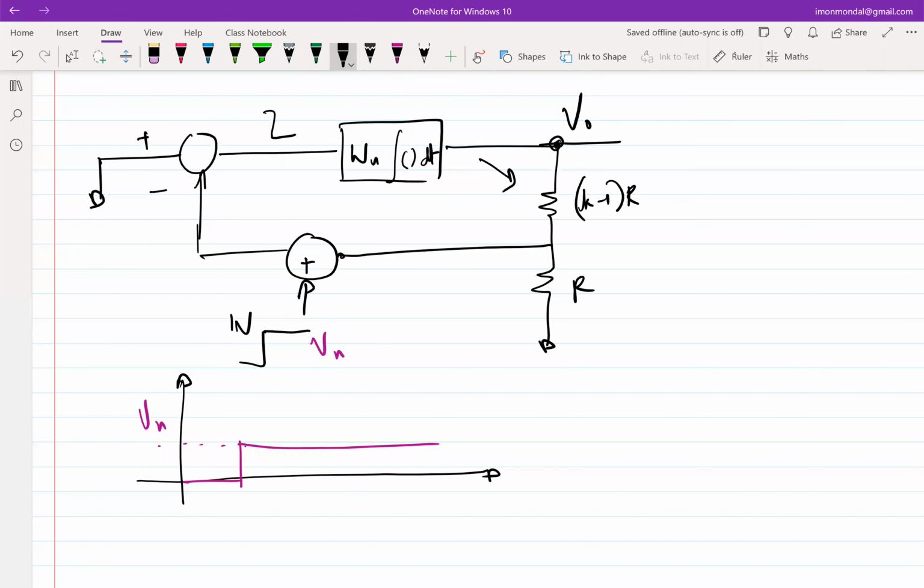Error will decrease, right? So the error voltage will decrease, isn't it? Steady state, we have to be minus. Again, go the backward route. At steady state, what is sacrosanct? Error voltage is zero. Error voltage at the input of the error amplifier is 0. Which means this has to be 0.